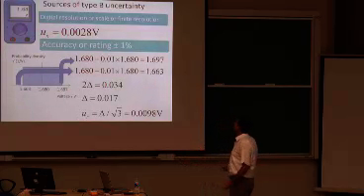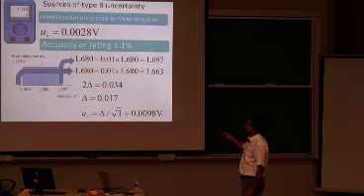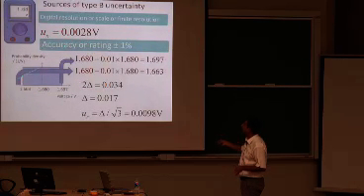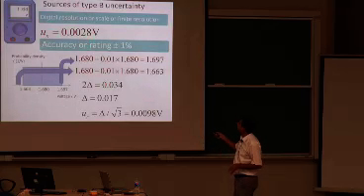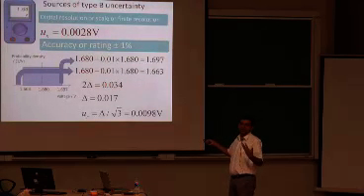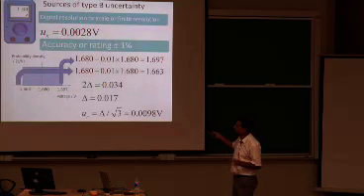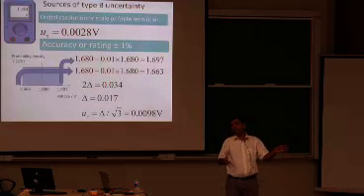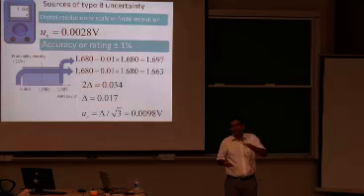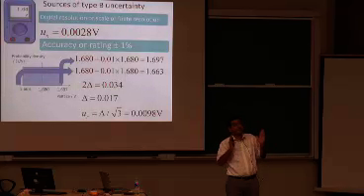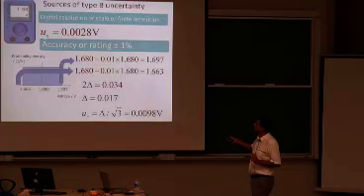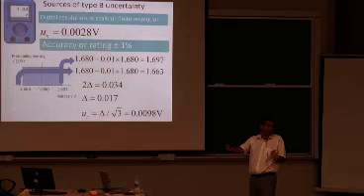Okay? So for example, we've seen one kind of uncertainty, which is a type B uncertainty associated with the scale. And we've calculated this to be 0.003 volts. Now I've just put in one extra digit that is churned out by the calculator because I would like to use this value later. So I put this uncertainty as 0.0028. The calculator will give me more digits. I just keep one more digit than I actually need, because in the arithmetic at the end I would just keep the number of digits that I really want. So this is the uncertainty associated with the finite resolution of this instrument.